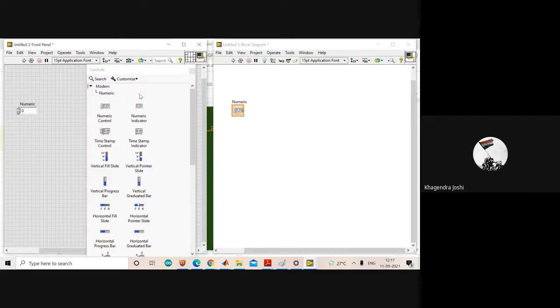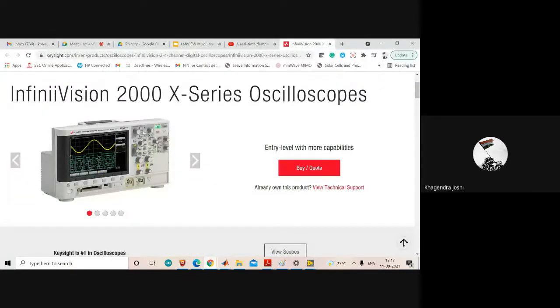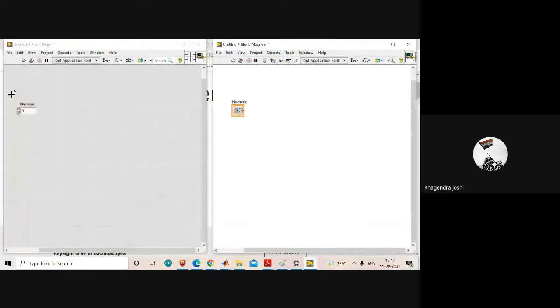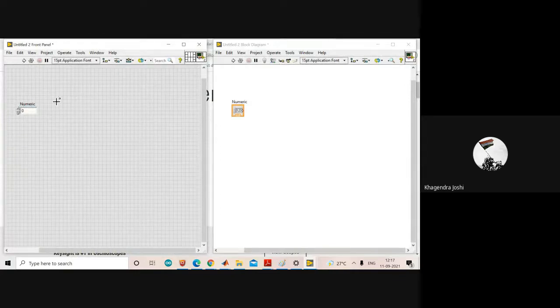So this is about LabVIEW. Suppose this rotating knob is there, it is somewhere connected internally to some circuit that is not visible, right? Similarly, in LabVIEW, whenever we drop any sort of control from the control palette there on the front panel, you'll see a respective node already gets automatically created there on the block diagram, right? So whatever you are coding will be linked, right?